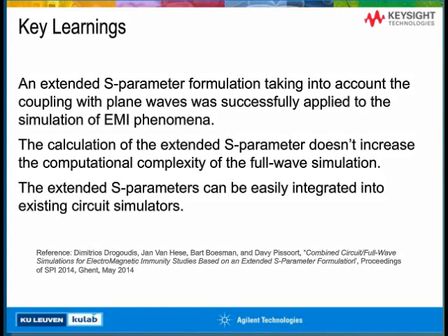What are the key learnings from this example? An extended S-parameter formulation taking into account the coupling with plane waves was successfully applied to the simulation of EMI phenomena. The calculation of the extended S-parameters doesn't increase the computational complexity of the full wave simulation itself. It's only one quite simple simulation. The extended S-parameters can be easily integrated into existing circuit simulators and combined with, for example, behavioral models of integrated circuits. For those who want to know more about this example, the reference shown at the bottom of the slide gives you all the details about the extended S-parameters.